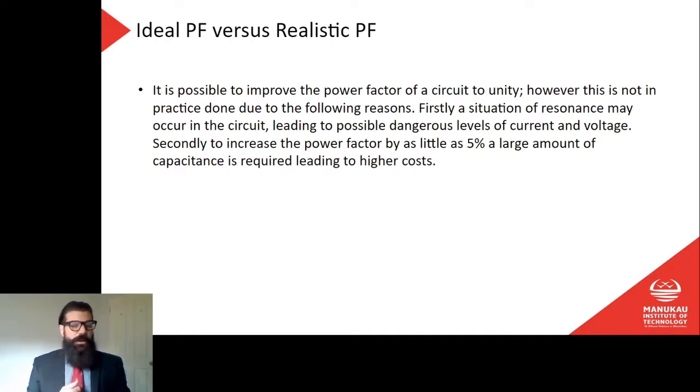Secondly, to increase the power factor by as little as 5%, a large amount of capacitance is required. It's leading to high costs. So although it will save us some money in terms of the power that we pay for, it will cost us some money. We have to go and physically install a lot of big capacitors.